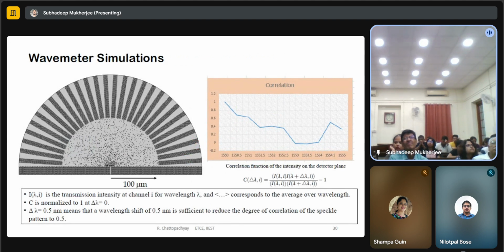So this is a photonic crystal, and the entire dimension is not more than 1 millimeter. This part is photonic waveguides, photonic crystals which can carry light at 1550 nanometers. And here is the random medium. These are nothing but air holes dug into the silicon, of the order of 80 to 100 nanometers, and they are randomly distributed. So it's a static random medium. Now when light comes in from this input port, it gets scattered and it has 24 ports. Each port will have some amount of energy going into it.